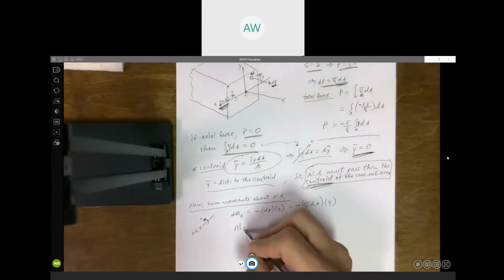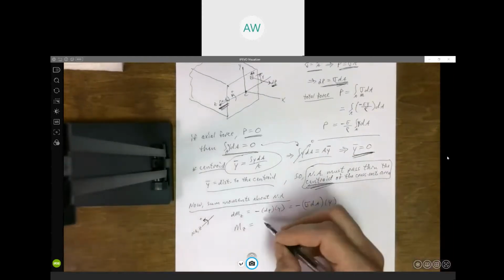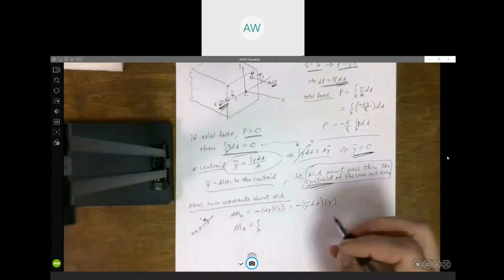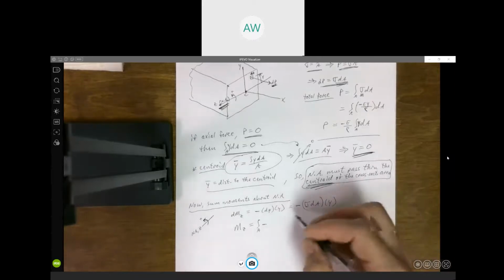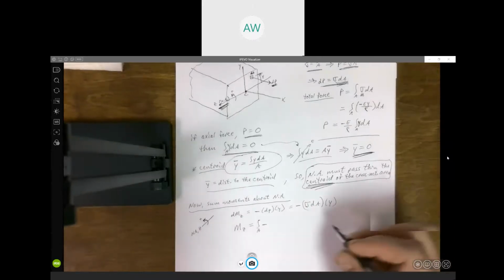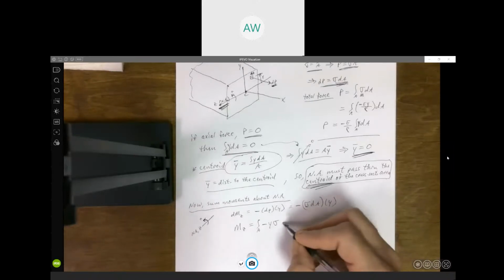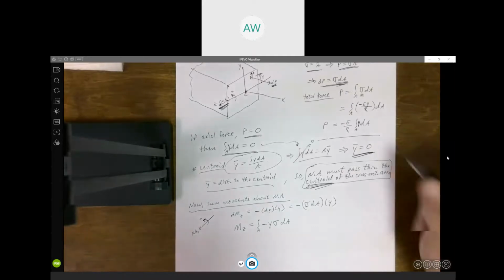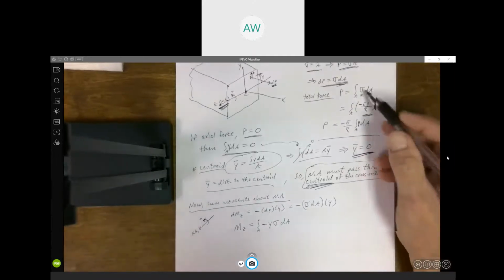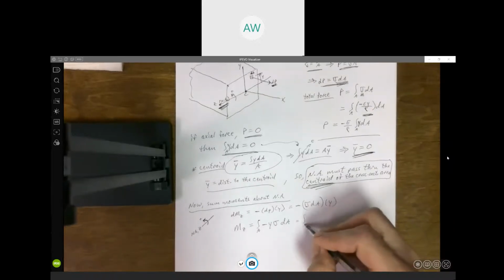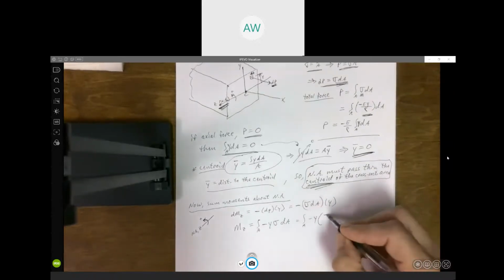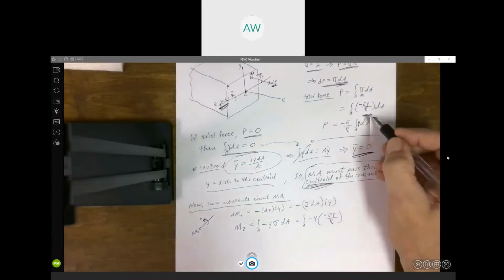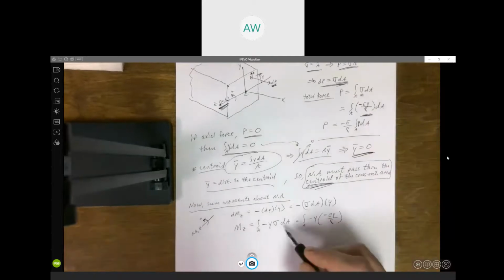So to get the total moment, Mz, it would be the integral over that entire area of minus, I'm going to rearrange things so I put my dA at the end, so minus y times sigma dA. Making the same substitution we did up here as well, for that stress, I know it is minus Ey over rho, substituting what we determined the stress was here.